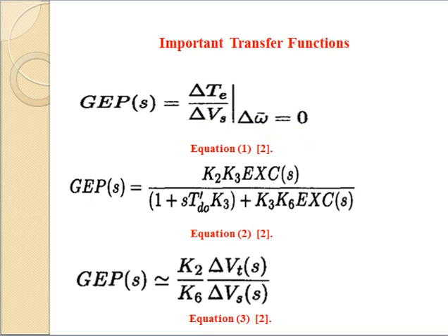I would like to tell you how this is generally obtained in industry: you are going to increase the inertia of the generator. So when you increase the inertia of the generator, there will not be any major velocity variation. So in that condition, if you check this transfer function, for change in Vs, if you check the change in T, you will get this GP of S. Now, GP of S is important because depending upon this only you are going to tune the power system stabilizer. This we are going to understand in some of the further slides.